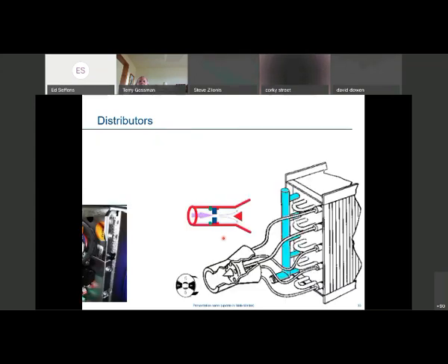Now the nozzle type distributor that Sporlan manufactures, internally there's a little cone, and this nozzle itself actually sits into this raised portion of the distributor. Okay, it just kind of sets in there, and there's a retainer spring that holds this in place. Now the G corresponds to the distributor type, whatever type that distributor is.